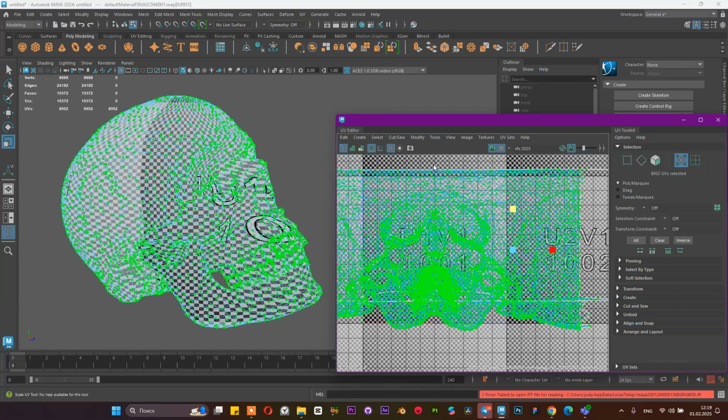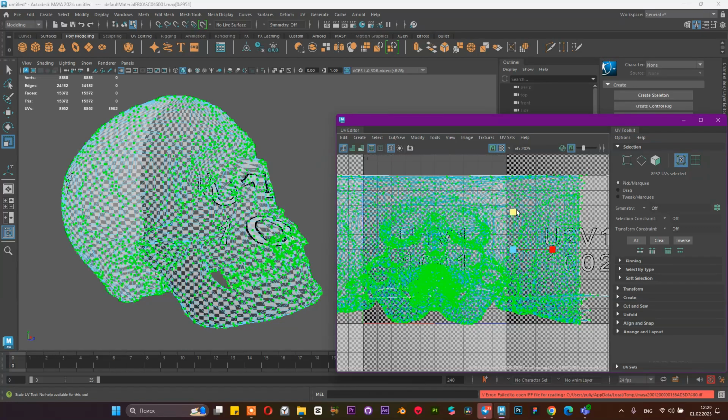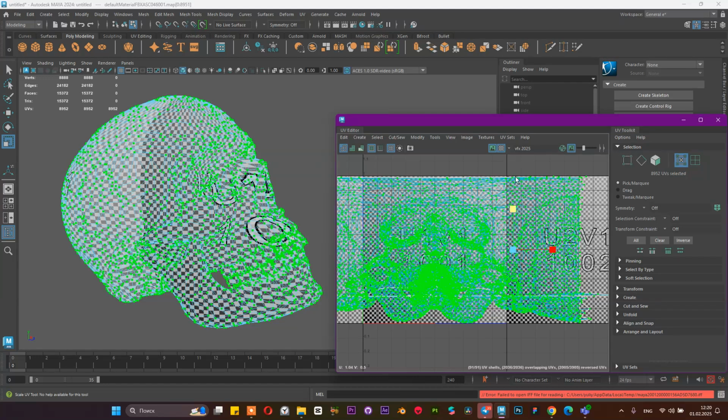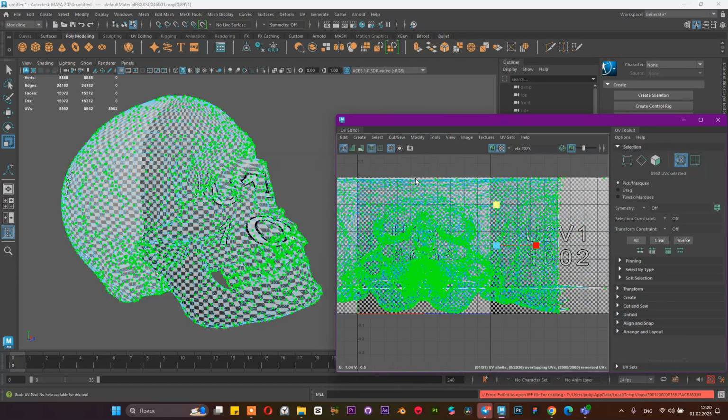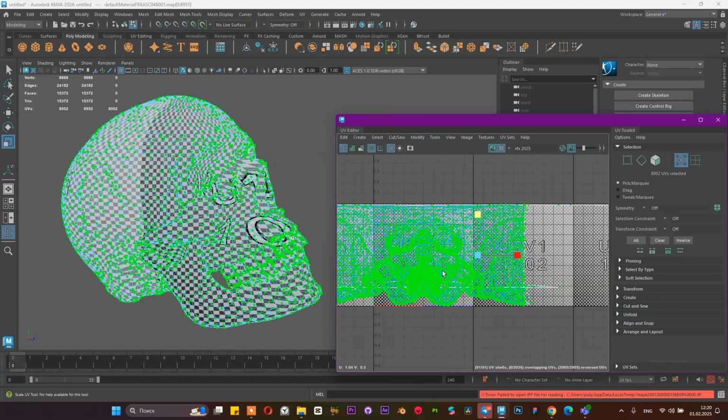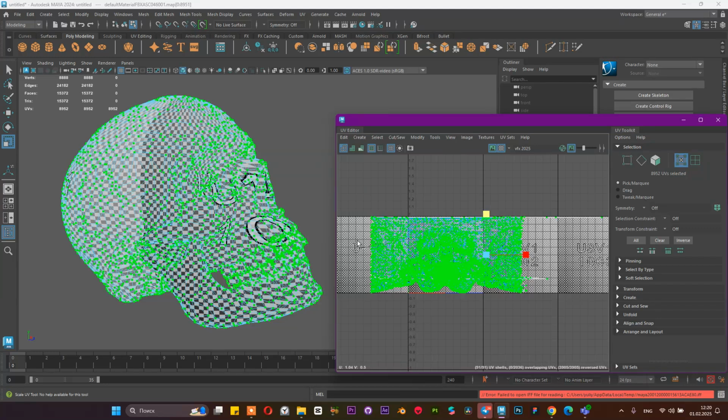For example, these objects can disappear two times, or maybe not disappear well. That's why you should check every UV should be between 0 and 1 without any intersection of this line. It doesn't matter if these vertices or UVs go wider to the left or right, but avoid intersections to the top and bottom. Wider doesn't matter, it's just duplicating this position.